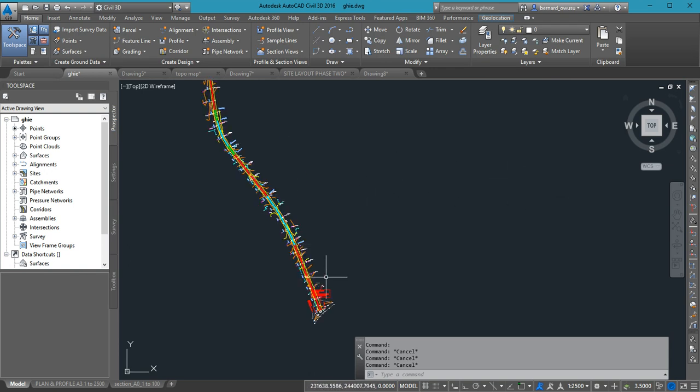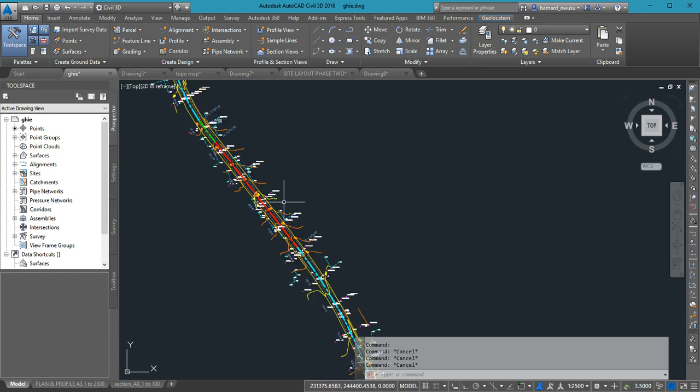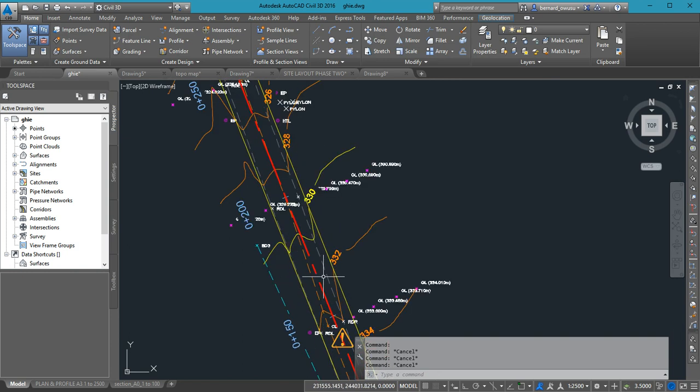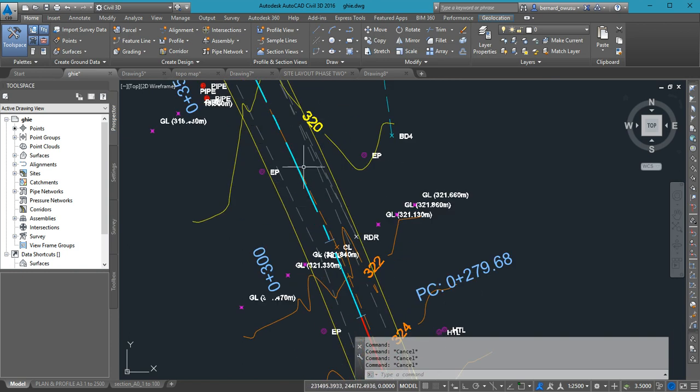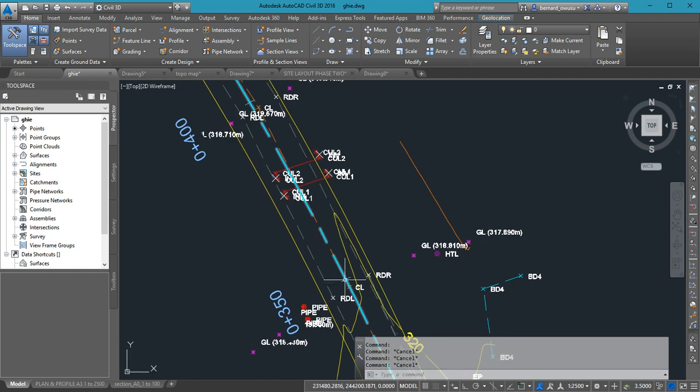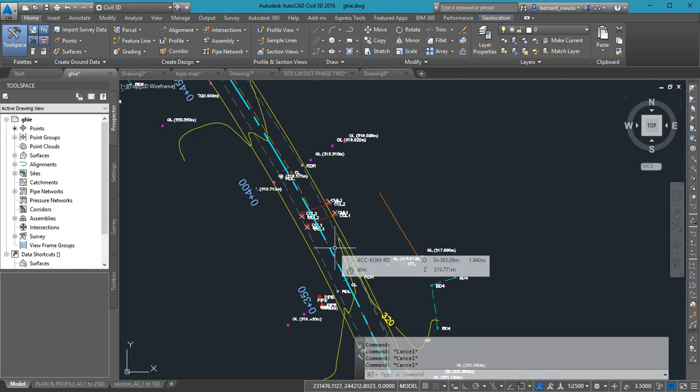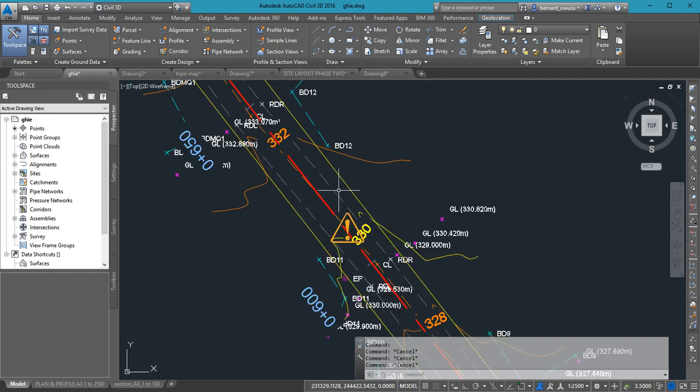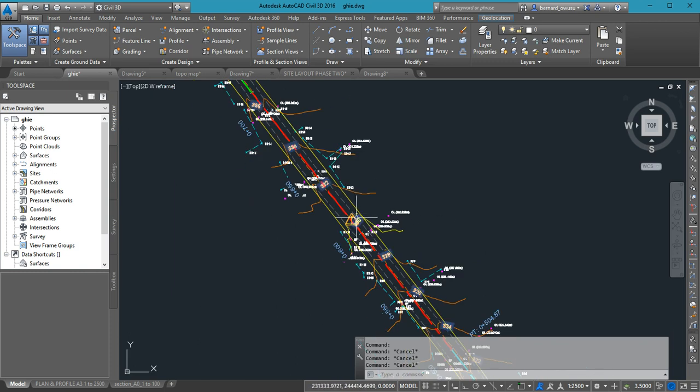Now you realize that what I've designed now is a design center line. You remember that we also included the width. Now this is just to guide us because of lack of time. If you look at somewhere here, you can do some editing, move the center line in such a way that you minimize the property impact. So you can zoom in and see whether your center line in terms of the boundary is affecting properties. So even before you get to the point of inserting corridor, you know what will happen.